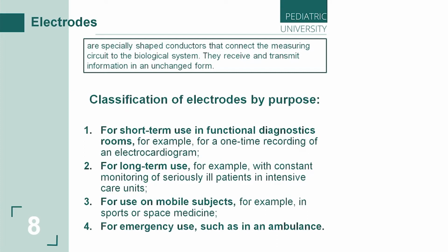It's clear that in all cases the specificity of the use of electrodes will appear. Certain requirements are imposed on the electrodes. They must be quickly fixed and removed, have high stability of electrical parameters, be durable, and not irritate biological tissues, etc. An important physical problem related to electrodes for picking up a bioelectric signal is to minimize the loss of useful information, especially at the electrode-skin contact resistance. Due to the presence of resistance, information comes to the signal amplifier in a modified, reduced form.